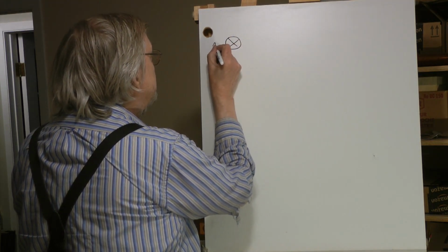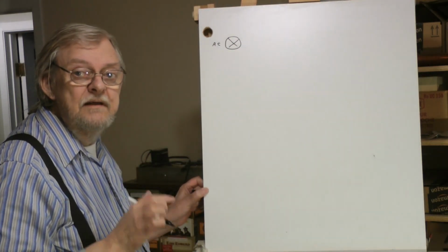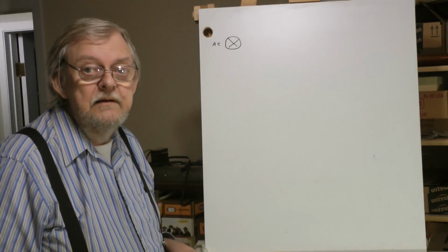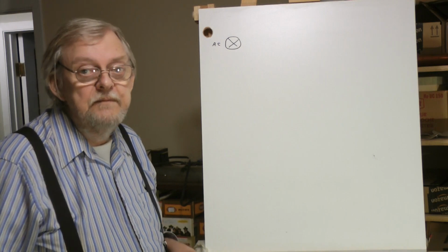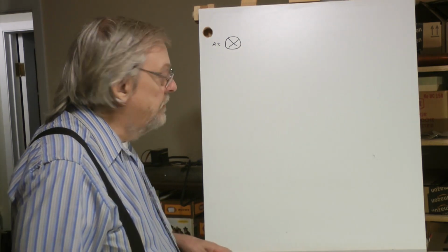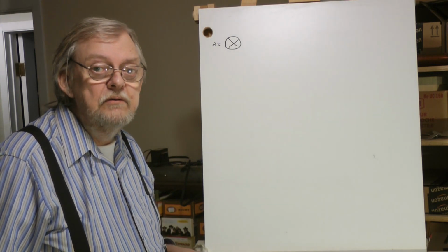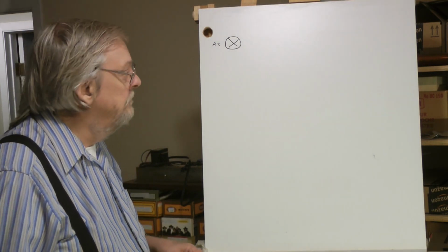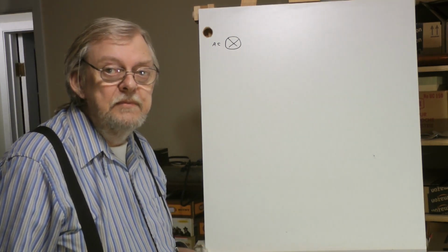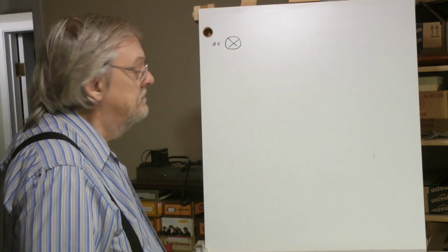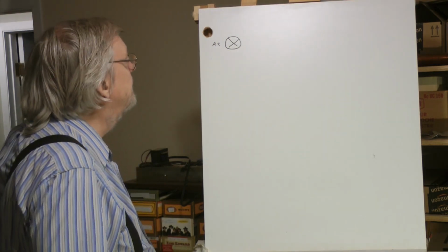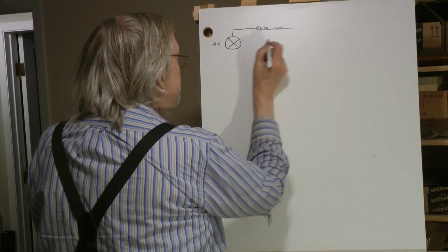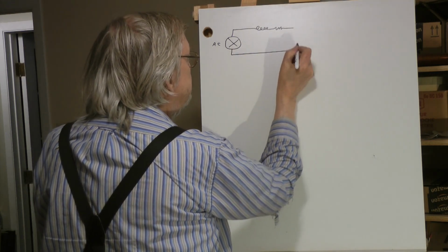The representation is an AC current generator. How that works is the strings are metal and they're magnetic, and they attract the field from the magnet in the pickup through a property called reluctance. And when you pluck a string, it actually vibrates the field because the field's kind of stuck on the string. And that field vibrating through the coil in the pickup causes an electric current. Same way hydro generators work. So we represent that with the inductance and the resistance inside the pickup.